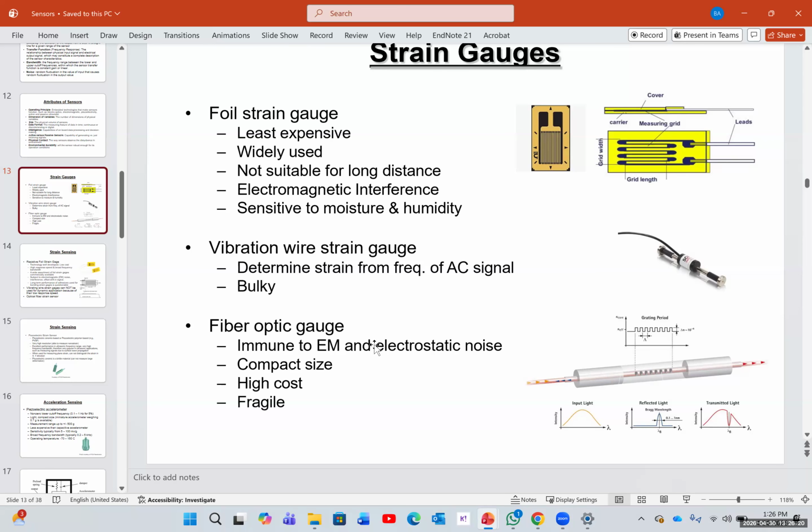If you want to send this, it's not going to go far. You need very large antennas. I'm not going to go through the equation, but you're just going to have something like 1 mile or so. So what you do is use a carrier signal. It's a very high frequency signal that carries the lower frequency signal.